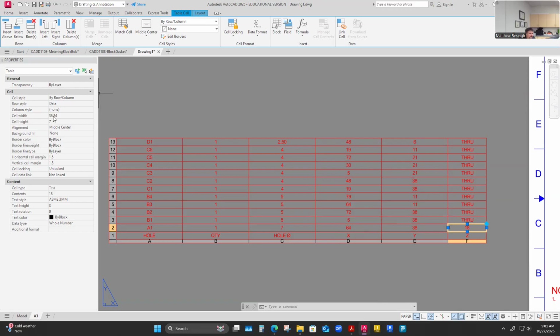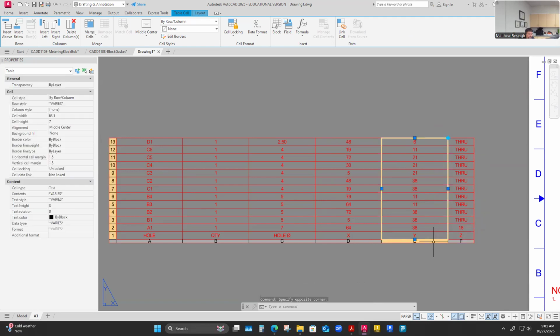Over here my properties panel is reading out my cell width as 36.84. I might just type in a number that's closer to a whole number just to keep this plainer and simpler. Like this is 27. So what if my cell width was 25 over on my tab? Then that's a pretty nice compact width, and it should handle all my other data. So I should be able to select here and say cell width. We're going to be at 25.